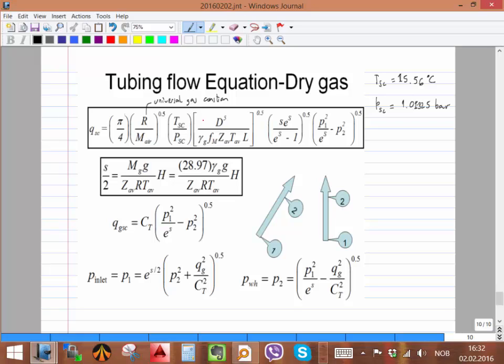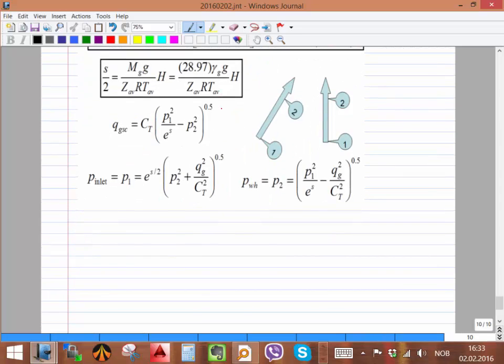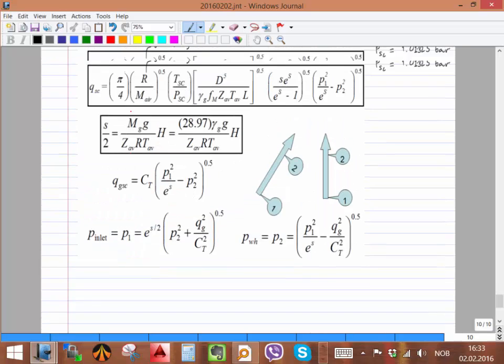So you have those two, you have the diameter of the pipe, and I think Professor Golan, for those of you who are taking natural gas, made the deduction of this equation. We don't want to go into detail, but I will give you the document, and if you have some free time, please read through it and see more or less the assumptions he's making. Basically it's assuming single phase gas. You don't have any liquid or any other phase. And it's also assuming that the gas is turbulent. Remember that you have the flow regimes in a pipe. All of you know turbulent, laminar? Who doesn't know turbulent and laminar? Okay, good.